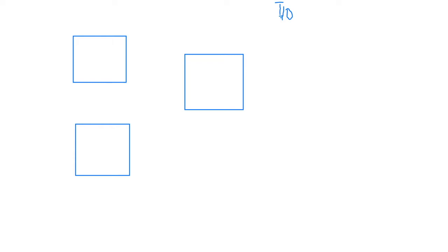Right, so we have a line. Now we know these ports or these lines can be used either as an input or output. This is a very simplified version of it. Of course, there's circuitry going on, which is controlled by ones and zeros. So somehow, if we are designing this, we need to find a way to tell the direction of the register. So the data direction register, which is DDR. Now we can have data direction register X, where X represents the port.